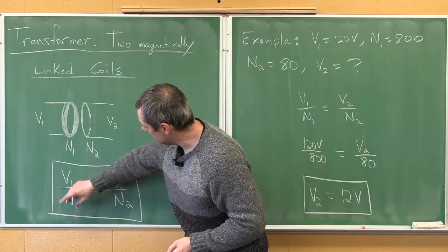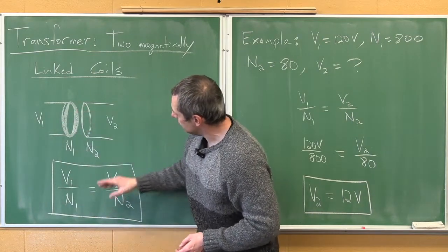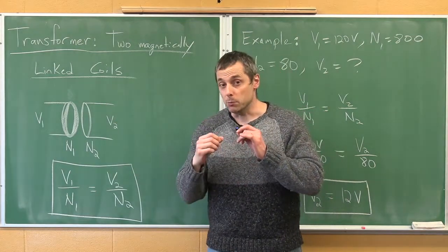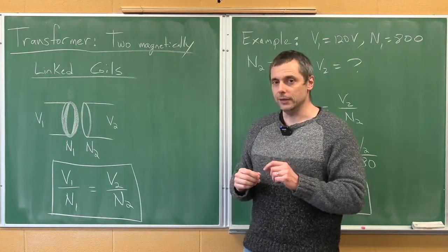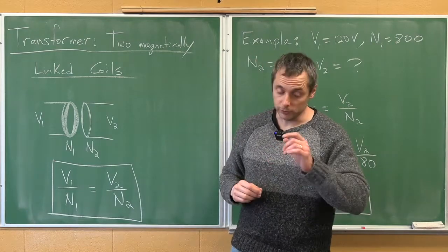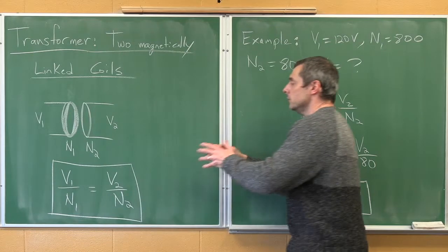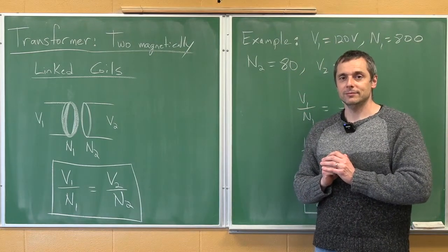Now the voltage relationship, you could find it by a simple ratio. Voltage here over the number of wire turns equals the voltage here over the number of wire turns here. And you could make less voltage, as we saw in the demonstration, but you could also make more voltage, as I mentioned. So let's take a look. Let me just create a pause to allow you to copy these notes down.